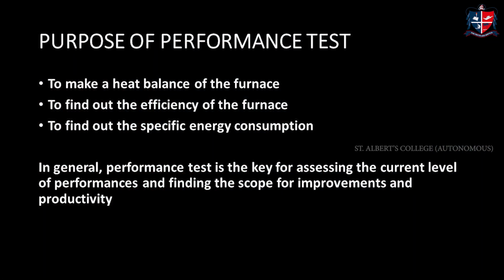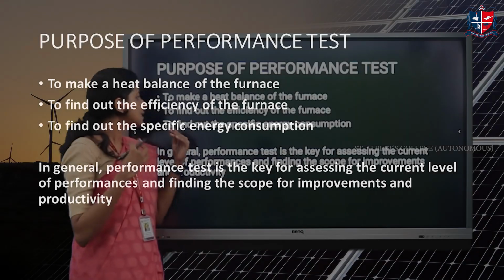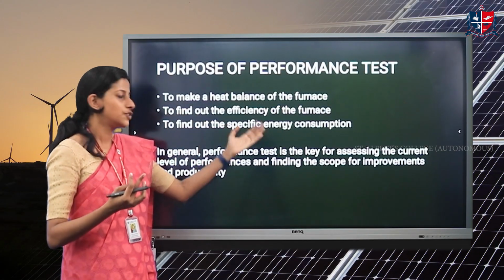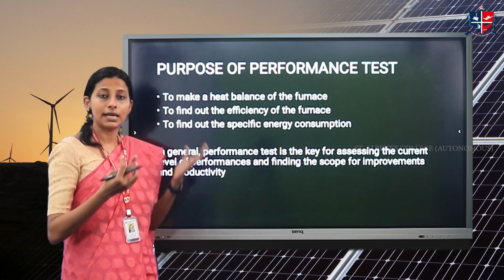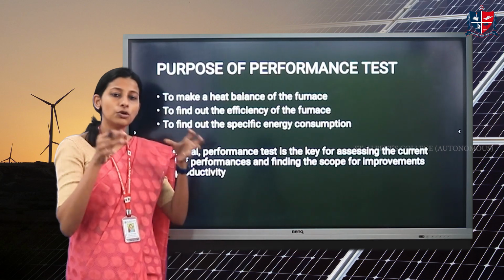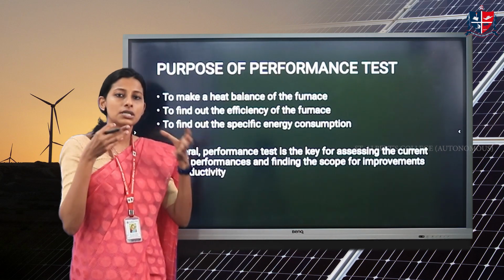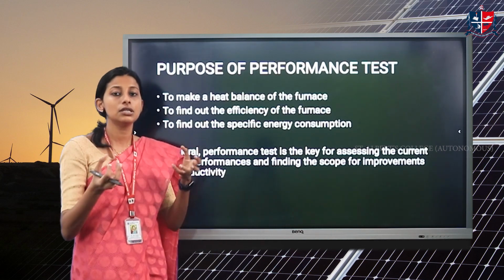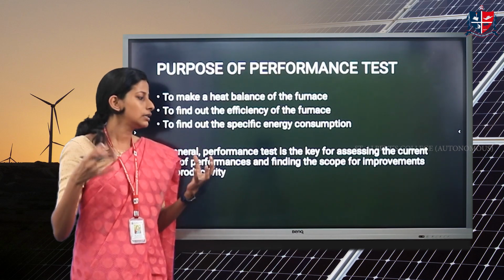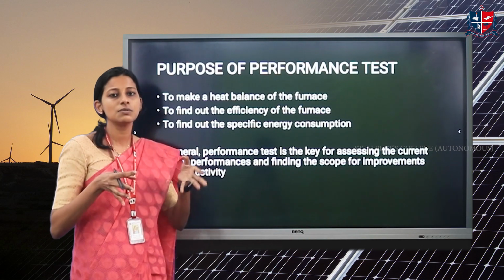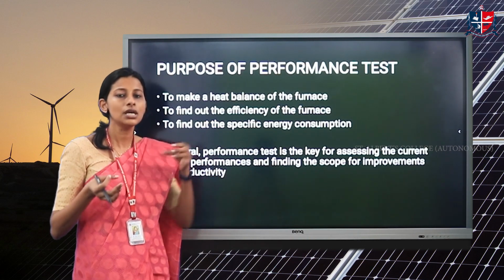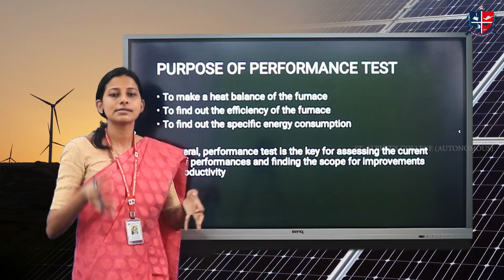Then why should we perform the test? As I said, the performance always has to be assessed because we need to know the efficiency, the energy consumption, and the heat balance. Heat balance means the amount of heat you give into the furnace should be sufficient to heat the material. The material is also called the stock. It could be steel, aluminum, or any metal. Anything that is to be heated, in furnace terms we say stock, or it can also be called billet. Billet or stock is the general term used for the material inside a furnace.